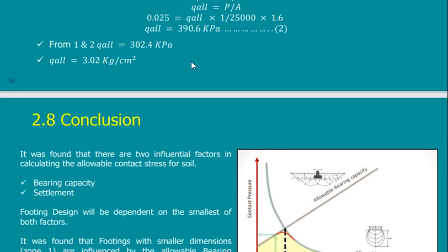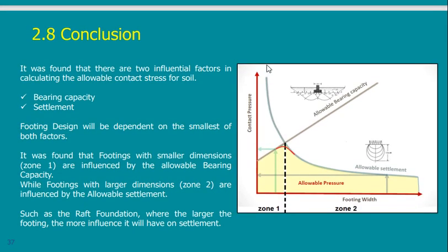So it means, as a conclusion, to end up this lecture, to calculate the bearing capacity of the soil, I have to do two things. I have to calculate the allowable bearing capacity based on the bearing capacity equation, which is the tradition in soil mechanics that we were using for a long time, and due to settlement of the foundation. I will get two numbers. I will use the smaller.